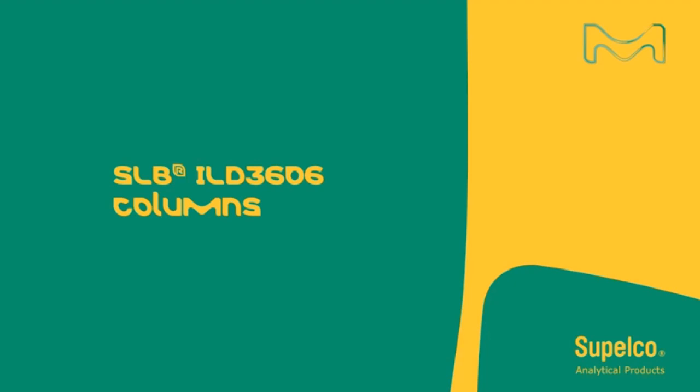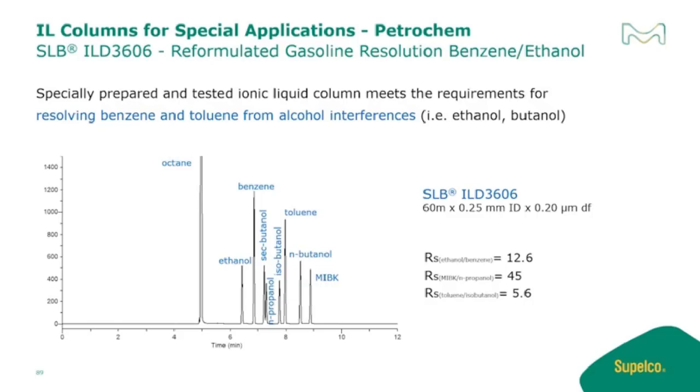Next one, a specially tested column, is the SLBI D3606. Again, the D3606 method is actually an ASTM method, the EPA regulated method for analyzing benzene and ethanol in gasoline. It requires a 2-column backflush system in the current version, and you must be able to resolve benzene and toluene from any other alcohols.